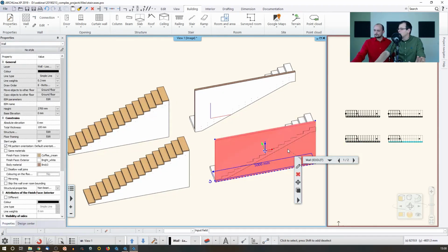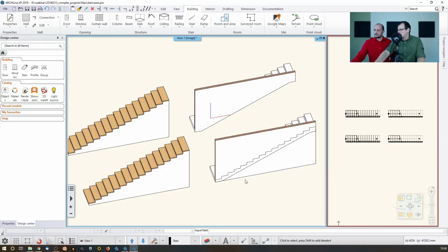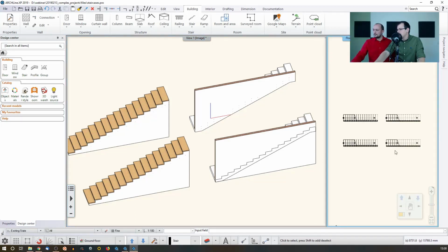Now, this one on the right-hand side is a bit different story. I cannot just turn on the same setting and it solves it, because then it would be at the bottom. It always cuts from the top. So we have to find a way to give a frontal profile to this wall, which tracks this. Obviously, I could open up the frontal profile settings and try to offset the nodes until I meet the staircase. But here's the thing: if the staircase is curved, for instance, this would be very difficult to do and time-consuming.